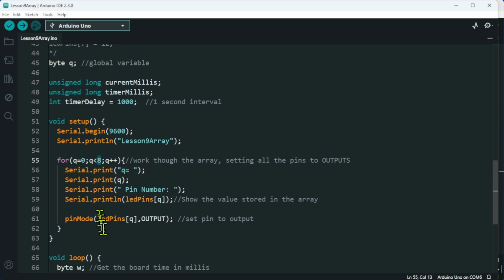If I put 20 in there, this loop will continue to run. The problem is it will overrun the edge of the array. It's one of those things that can happen on the Arduino. Other boards have some protection put in to stop that, but on the Uno it's very easy to start reading other bits from the memory that are nothing to do with the array that you are working in. So very simple. The for loop is working through one element at a time,